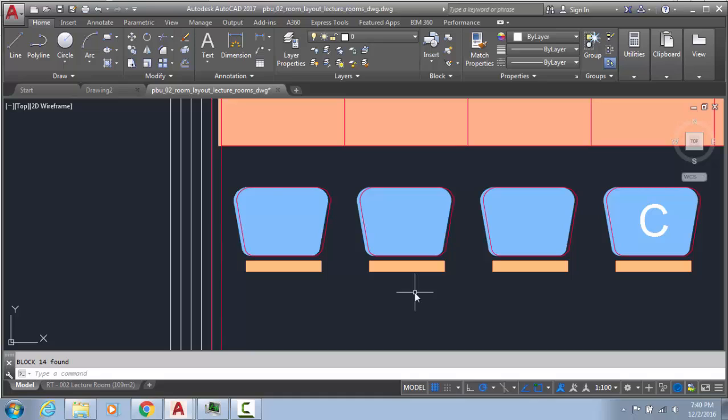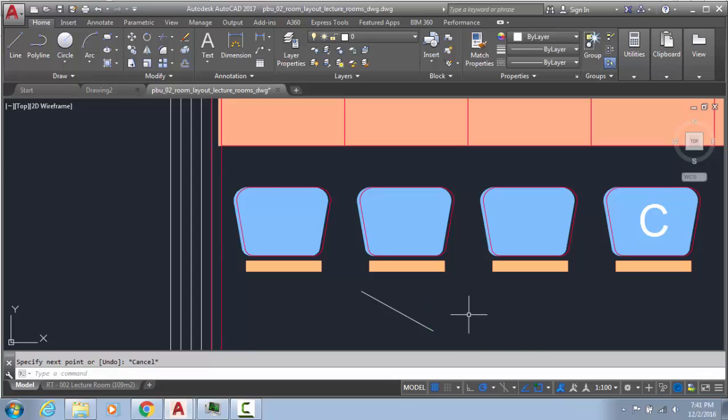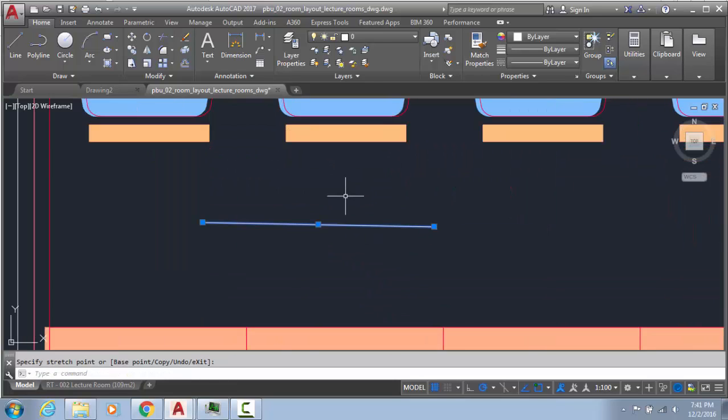But this is the biggest mistake they make, because if I select the drawing block, what I am watching, I am not getting the pick point. And what is the pick point? For example, I am making a line, sorry, I am closing the dynamic option, again line. Now if I select this, these are the grips. The first is the end grip, the second is the second end grip, and this one is the middle grip. Grip editing is also a very interesting feature. It's not a command, it's a feature of AutoCAD. Further on, if someone asks, I will show you how to use this.